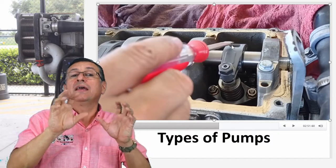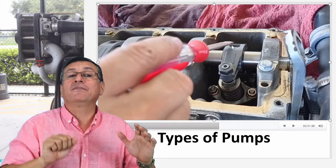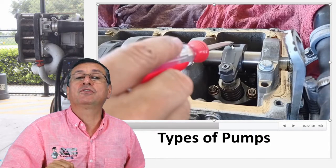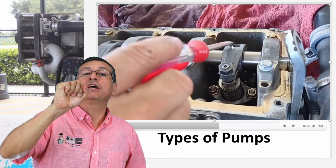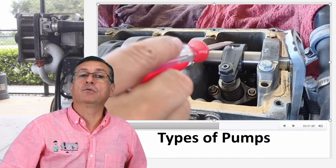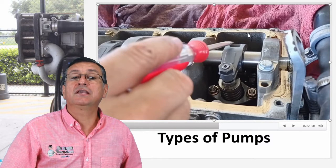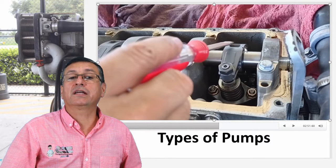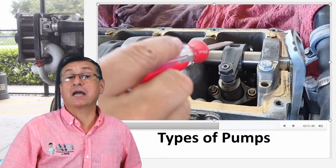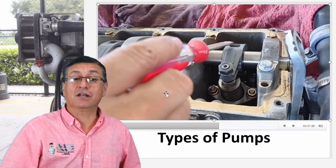When the valve starts, when the valve finishes, when the piston finishes the compression stroke, the injector opens and sprays the fuel and produces the explosion. Yes, this rocker arm is connected on one side with the camshaft, and on the other side opens and closes the injector. Let me show you this.